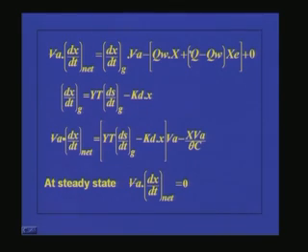This is the biomass leaving the system, one part because of sludge wastage, and the other going out through the effluent from the secondary sedimentation tank. The 0 is because we assume the biomass coming into the system is negligible compared to the biomass concentration in the aeration tank.